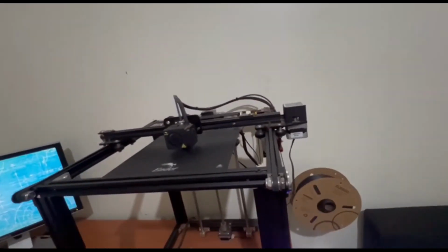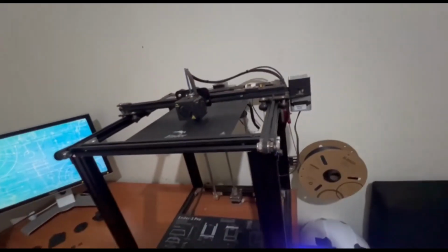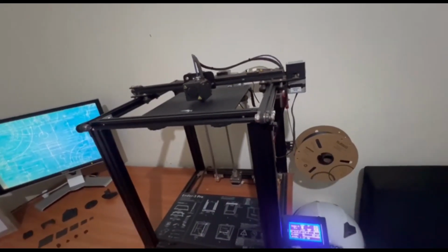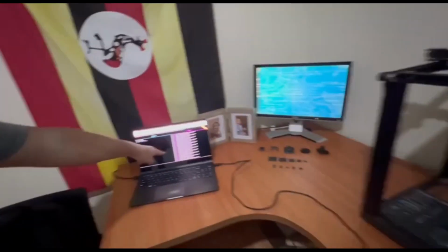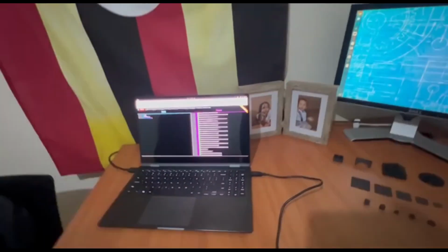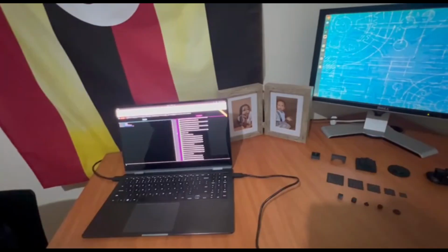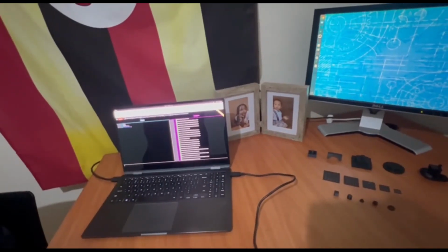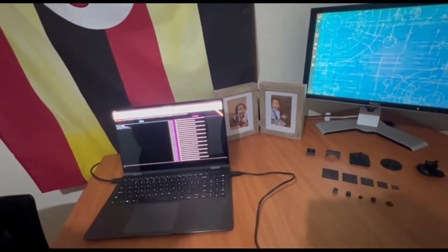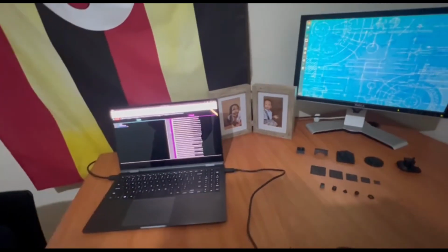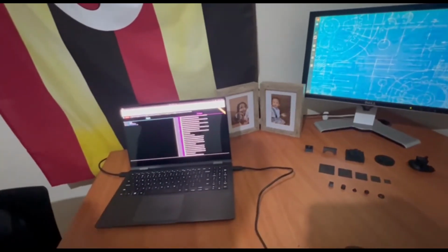You can see the nozzle head on our printer here is starting to move around and print that cube from our Quick Start. And over here on the screen, you can see all of the G-code commands are being echoed back to the web G-code sender here, so you can see what's going on and monitor things in real time.